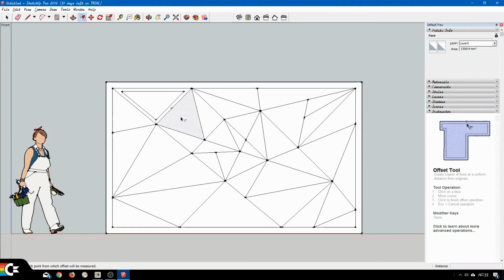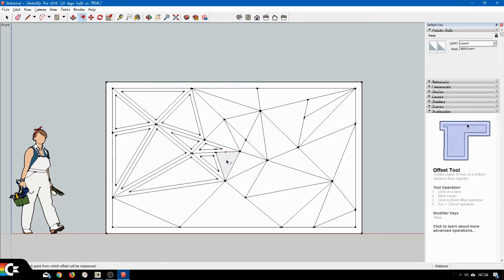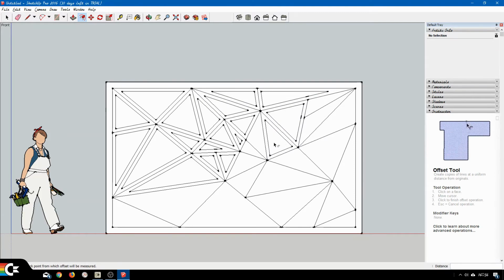And once I've done it once, I can double click on the rest of the triangles and it will inset it by 50. Be careful you don't move the mouse by accident, because if I move the mouse while I'm clicking, it will do that. So I'll have to undo that. Click once, move in 50, type in 50, enter, and now I can continue to double click. If you ever get something that looks odd, don't forget you can always rub lines out and start again.